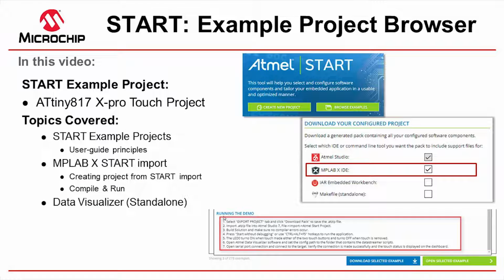So continuing a series using AVR in MPLAB X, we're going to start with importing an MPLAB Start project. MPLAB Start is similar to MCC in the fact that you're able to configure drivers and software for a microcontroller. Also, it has a built-in example project browser, which we're going to be demonstrating, and can export to a range of different IDEs, including MPLAB X.